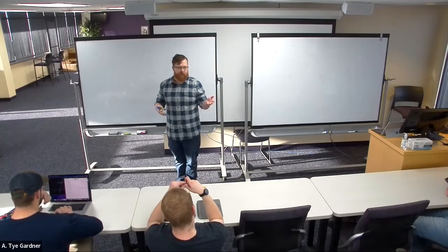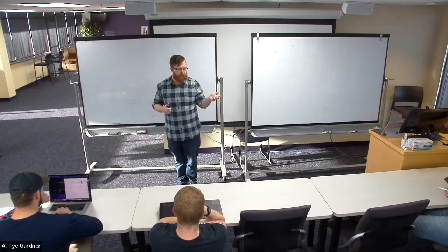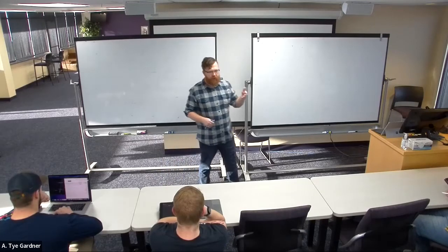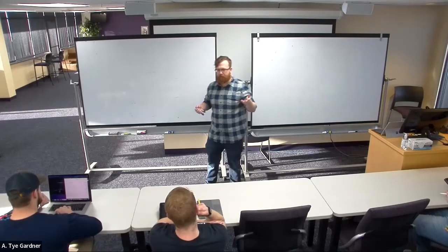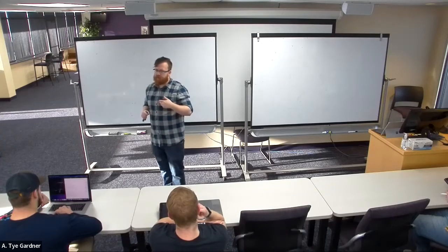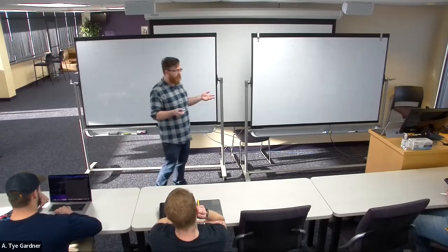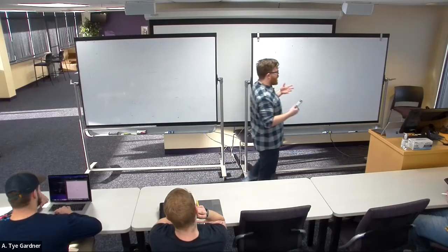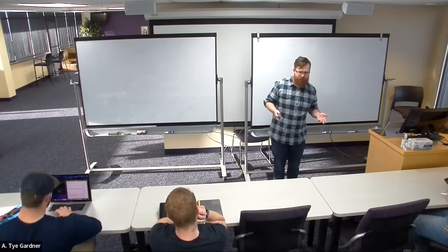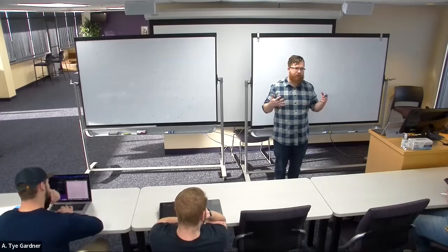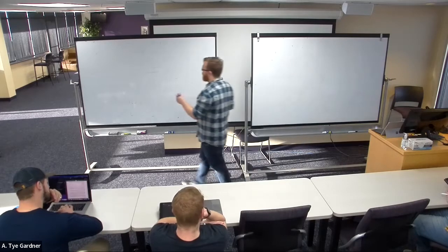And so we built circuits with digital inputs, just using a resistor, and we can throw a switch. But those resistors are big. And it turns out no matter what we do, when you get down to micro scale or nano scale devices, which is what's in your phones and tablets and PCs, big resistors are bad. We can't do things quickly because the bigger they are, the slower they go. And so what we want is a device that functions as a switch. And that's what a transistor does when we start considering it as a digital device. And we're just going to draw them like so.